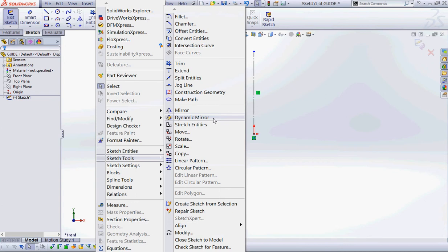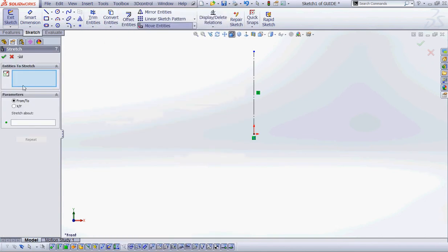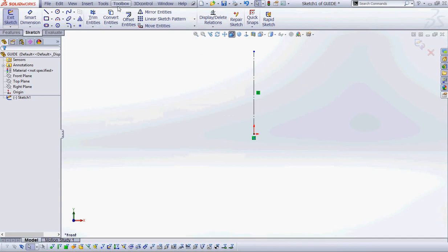All right, so I can click on this origin. I'm just going to draw a line straight up vertically, and notice I look for that little vertical symbol to apply that. And I'm going to right click and go select, and notice it placed a center line.